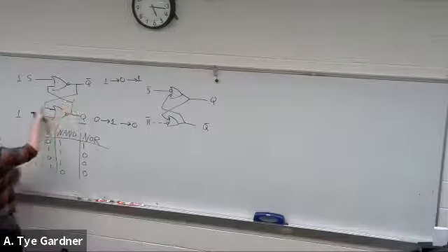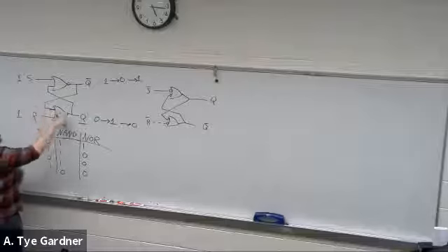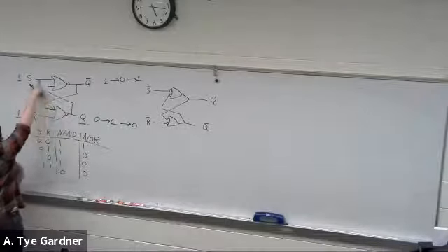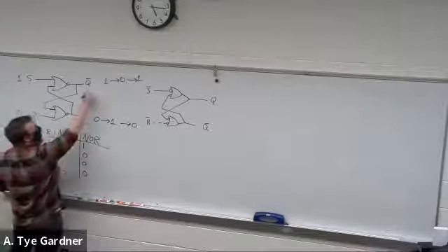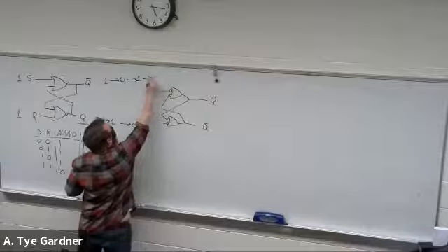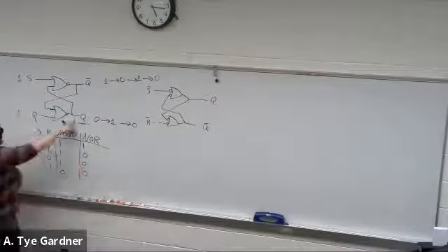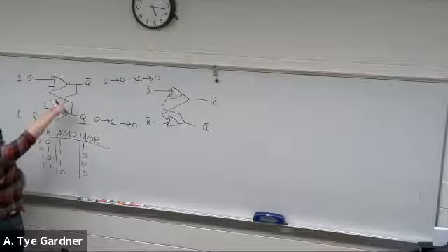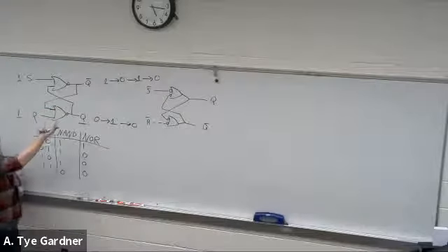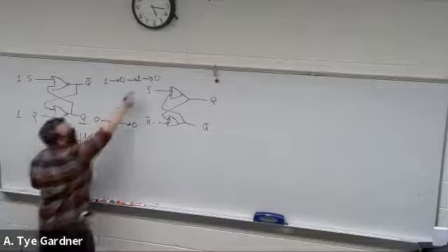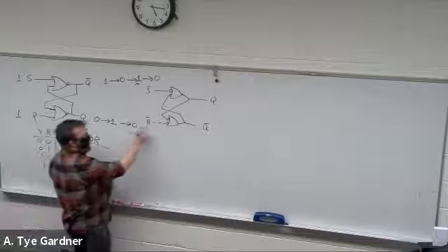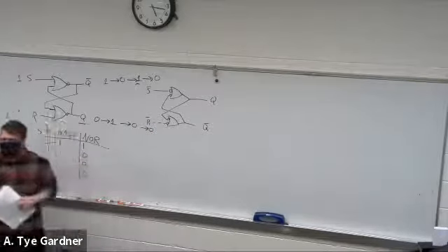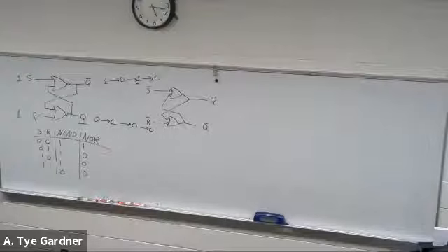So I have a 1 here and a 0 here. So 0, 1 says that my Q bar should be 0. And then Q, well, reset is 1, and that was 1 before at the initial state, right? So we've raised them at the same time, so I'm still in this state. So 1, 1 is also 0. But it doesn't make sense, right? That's a problem to say that they're both 0.